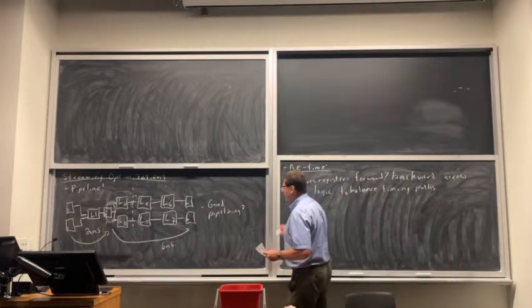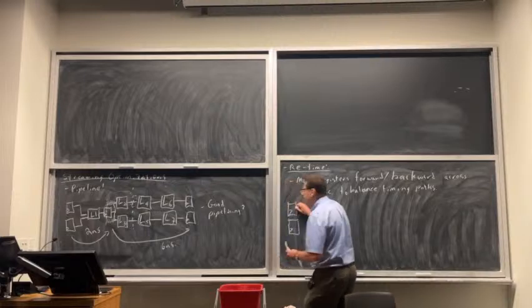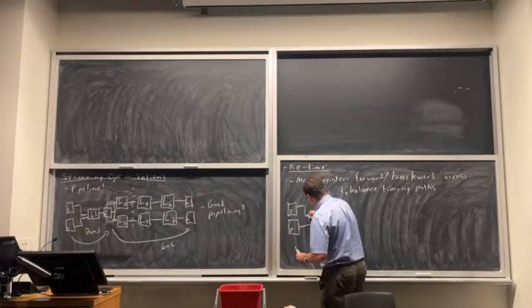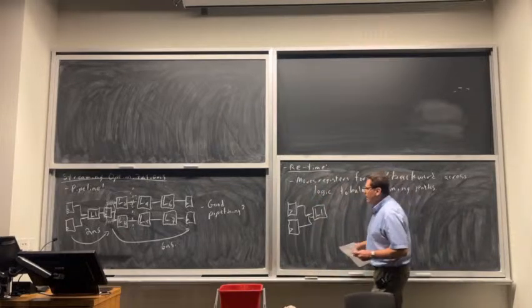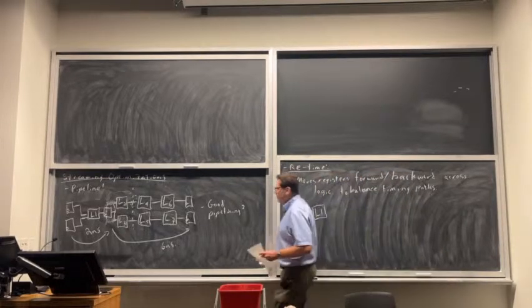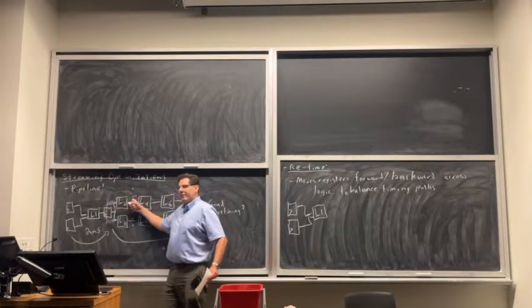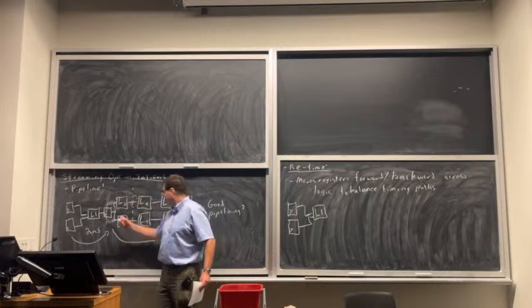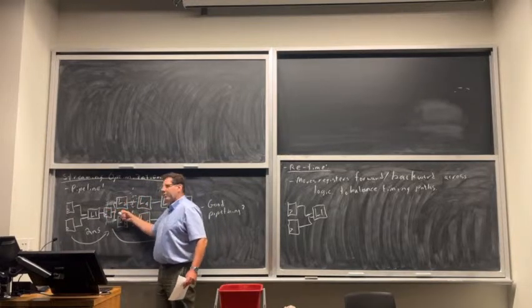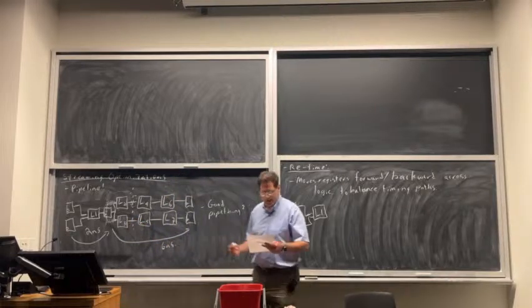Okay, so if I retime this, let's just draw this. I have 2 registers going to L1. I used to register that, but now I'm going to move this register basically up to its fan out. And I need to make a copy on each one of these because it's got to be a cut line again. So there was 1 register here, but because it goes 2 places, when I move it across these LUTs, I have to put 2 registers in. It's like a different cut line.